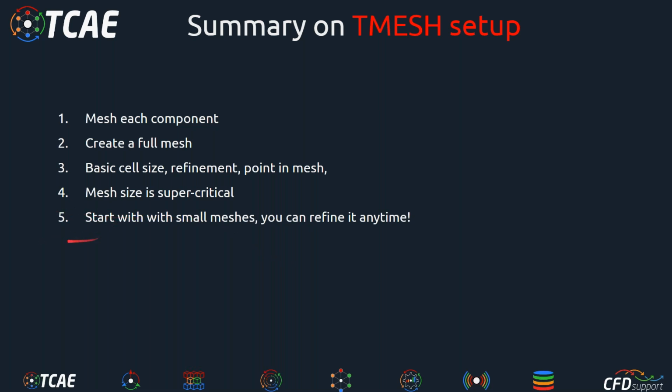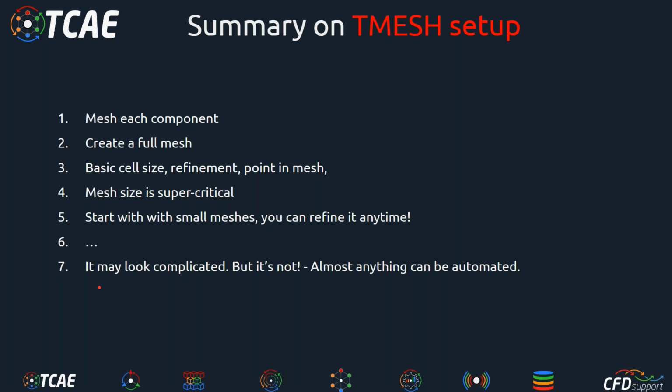So we definitely recommend to start with smaller meshes, to make a few quick iterations in the beginning to make sure you did everything well, and then you can always refine the mesh, and you can always go for big simulations that aspire for, I would say, accurate results. But I definitely recommend start with small meshes and quick simulations because it allows you to iterate in your process in the beginning.